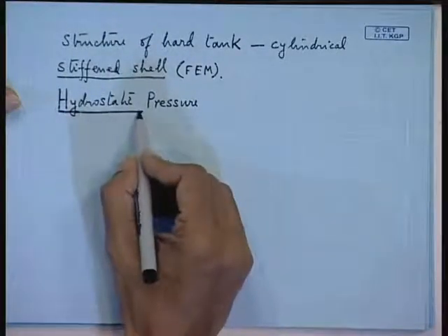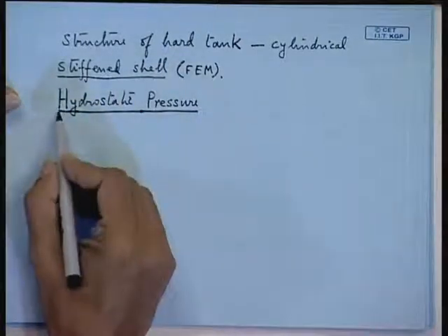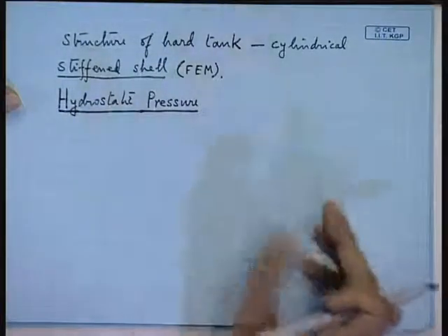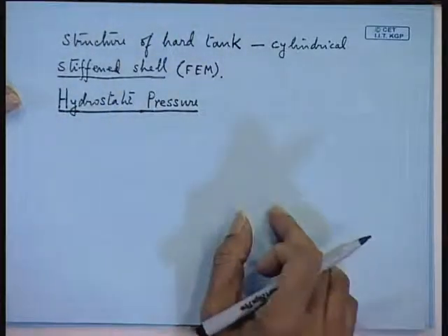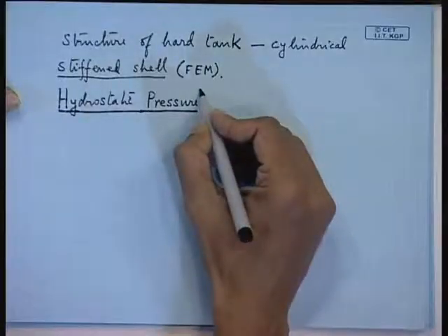I do not know whether you have studied the mechanics of this: a curved arch or panel has more strength than a flat panel against buckling, is it not? So, all these hoop stresses will come. That is why in the ROV or in the submarine you will find the shell is curved, because of resistance to this hydrostatic pressure.